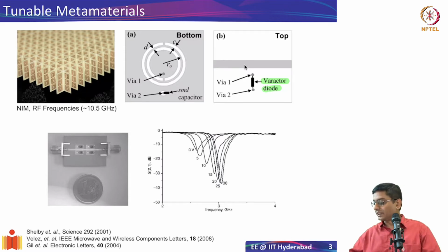If you do that, we'll see that it behaves like a notch filter, and the transmission spectrum S21 exhibits a dip at a certain frequency, that is the resonance frequency.